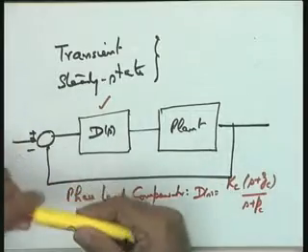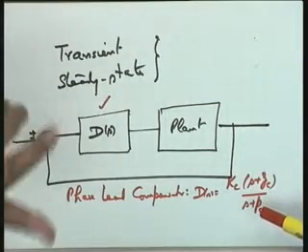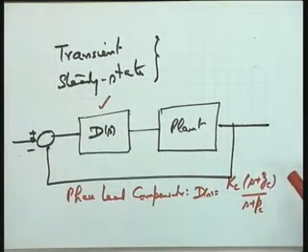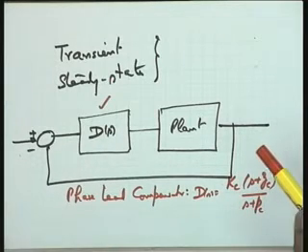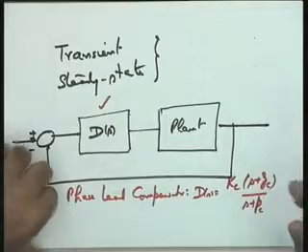So there are three parameters of the compensator: the gain Kc, the pole and the zero. If you recall an op-amp circuit given to you, its transfer function resulted in this type of model. There were three values, zc, pc and Kc, which were to be decided from the different values of resistors and capacitors in that op-amp circuit.